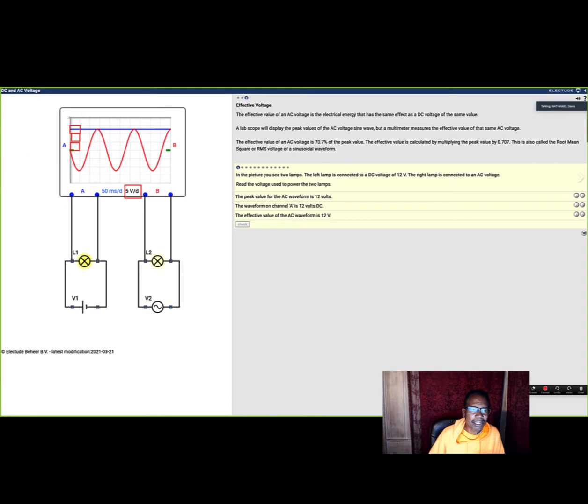And this goes up to 20 up here. So from here to here is 5, then 10, then 15, and right in the middle that should be somewhere around 12. That's 20, so from 0 to top is 20 volts. That blue line, what this last scope is showing you on the left, is at 12 volts.